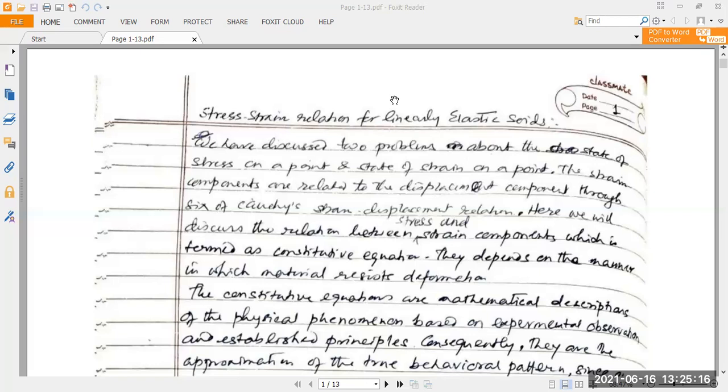We have discussed the strain as the deflection per unit length of the system itself. But what we have considered, for a particular cross section, the stress or this resisting force is same and uniform throughout this length.